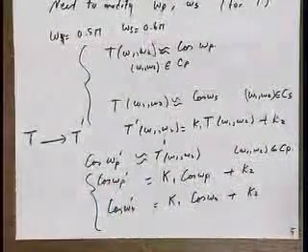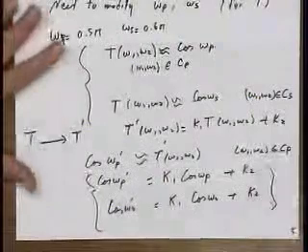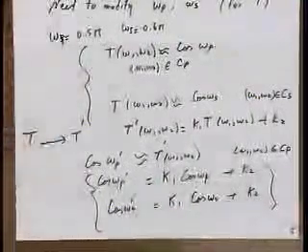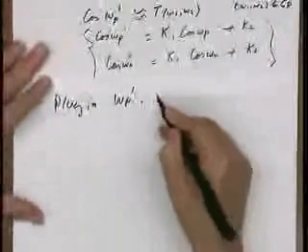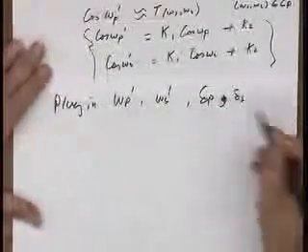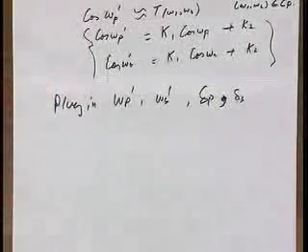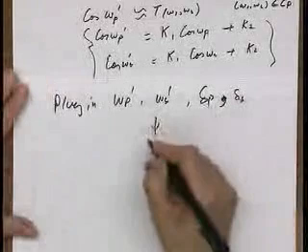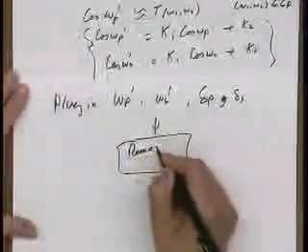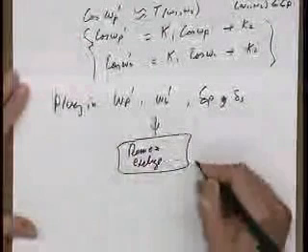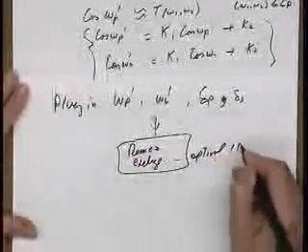Okay, so now we have these new values of omega p prime and omega s prime. Plug in the new omega p prime, omega s prime, and the delta p and delta s. You notice delta p and delta s hardly ever cause any trouble. They get translated straight from 2D to 1D, from 1D to 1D, they remain the same. But plug all of this into the Remez exchange algorithm to design an optimal 1D filter, a new optimal 1D filter.